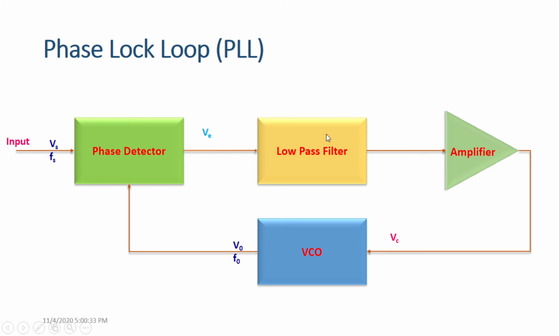or simply I can say that the PLL is in the idle mode. It is not doing its work because the input signal frequency we have is out of the capture range. At that time the PLL will sit calmly. I can say that the PLL is in the idle mode. It has not turned on its operation. So this is all about your PLL.